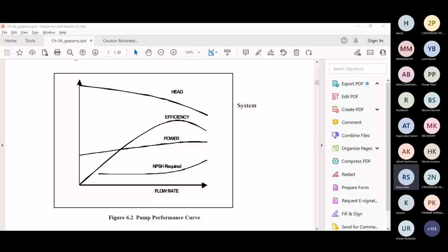So you have to add class A solvent at a rate of 10 liters per minute, so how will you add it? There is no other possibility. So you can use a PD pump, not an issue, but you should give proper safeguards so that there is not an incident like fire, or in case of leakage it should not form any vapor cloud or any incident. From a safety point of view you have to think. Okay, thank you, sir.